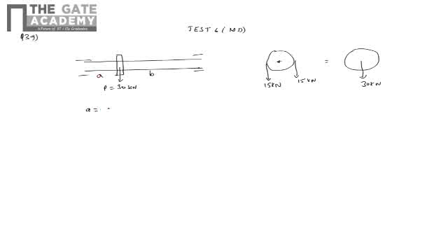So dimensions: A is 90 mm and B is the total length 250 minus 90, that is nothing but 160 mm. Now it is like a shaft or a beam, with a load at the center of 30 kilonewtons. The reactions, there will be some reactions R1 and R2, and if you draw the bending moment, you'll get to know that the maximum bending moment occurs at the point where the load is acting for an eccentric concentrated load.